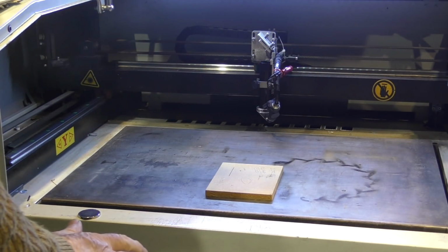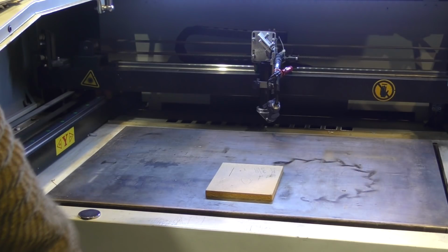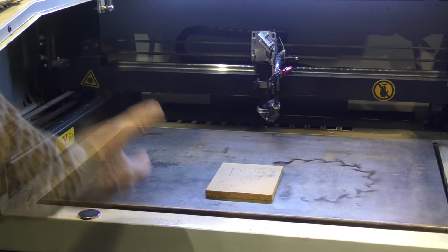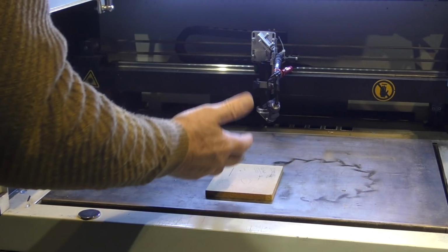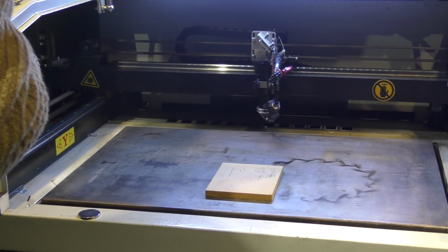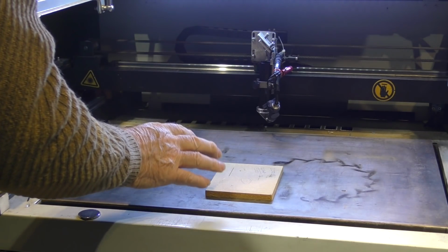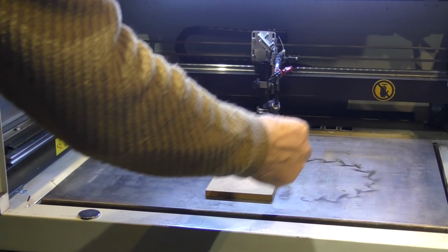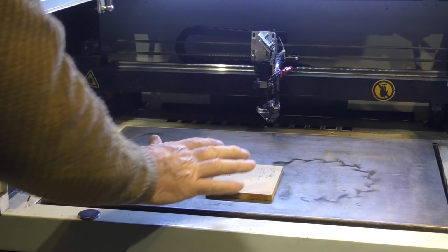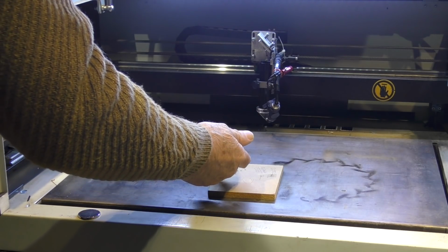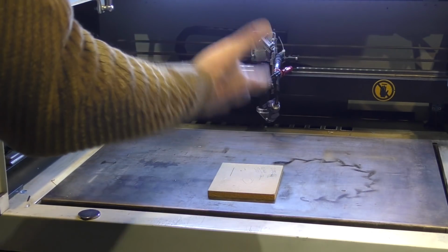Air assist on its own is great, but it needs something else as well to help it, and that's extraction. I've been running this machine without extraction on it, so you can see the way in which the smoke goes up in the air, especially during engraving, because one of the things you don't want to do during engraving, as I've demonstrated to you, is to blow the fumes back down onto your work, because that's how you paint them brown. What we try to do is to get the smoke to come up in the air, but coming up in the air only fills your cabinet.